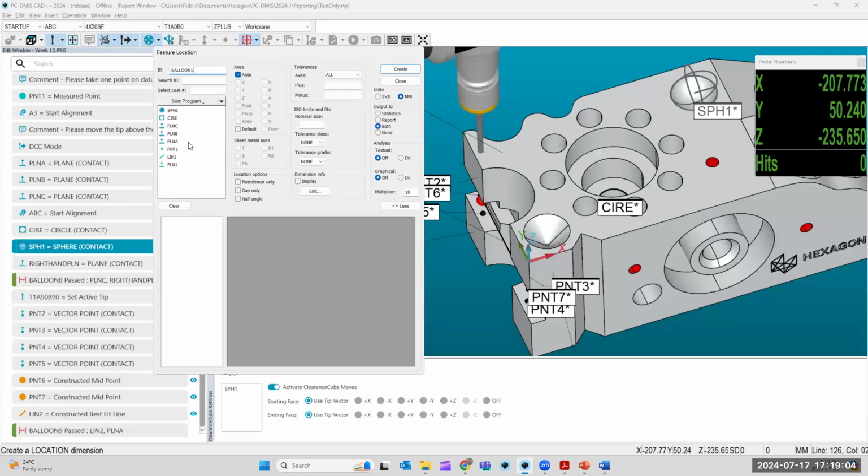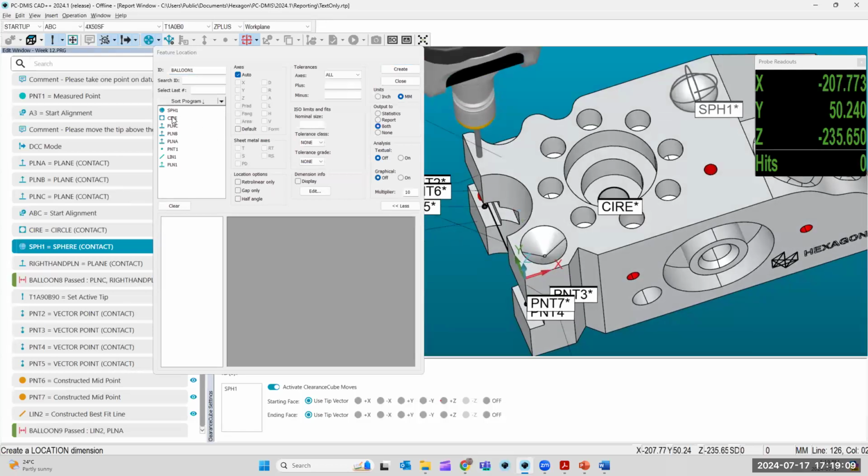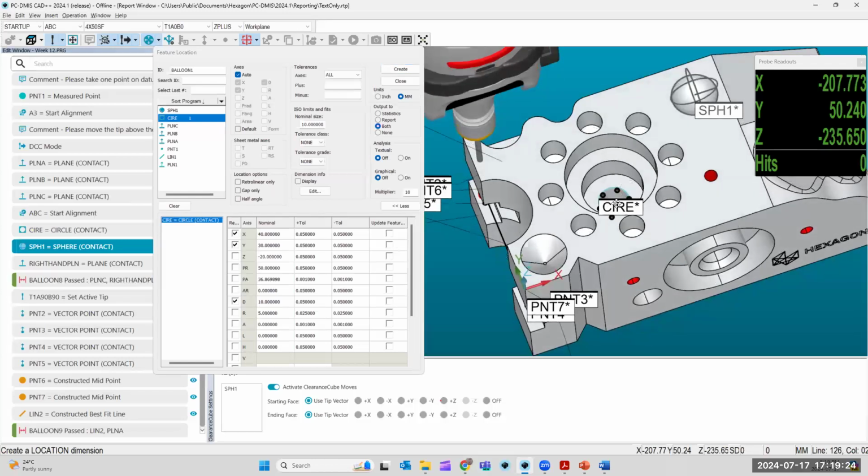Okay. So now that I have that, I'm going from circle E. So I'm looking for the position of circle E. I click circle E. I don't need to compare it to anything else. I'm just asking, what's the position of circle E relative to my origin? That's where it really matters what type of alignment you have, because circle E's position relative to an ADB alignment is X0, Y0, but relative to an ABC alignment it's X40, Y30.